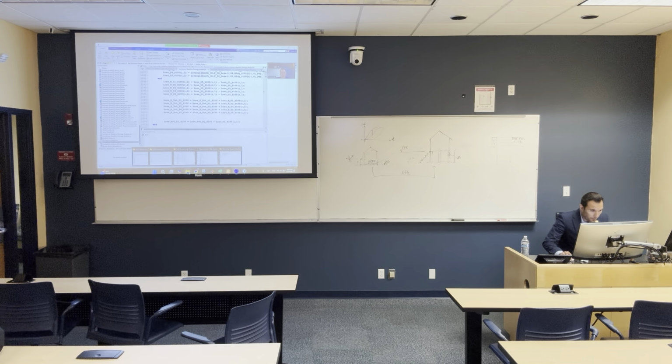This data is without elevating water sensitive components. If we elevated the water sensitive components, we are going to use this Excel sheet. Same thing with the 3D fragilities. I have one called archetype F1 3D and one F1 3D elevated. Same thing for archetypes 2, 3, 4. So I only have 4 archetypes with elevated components.